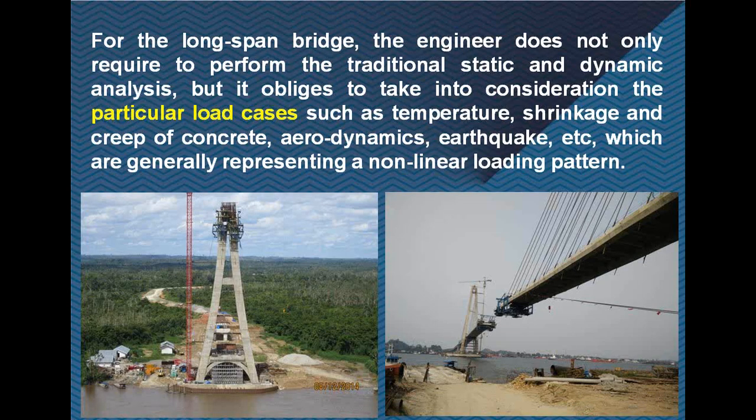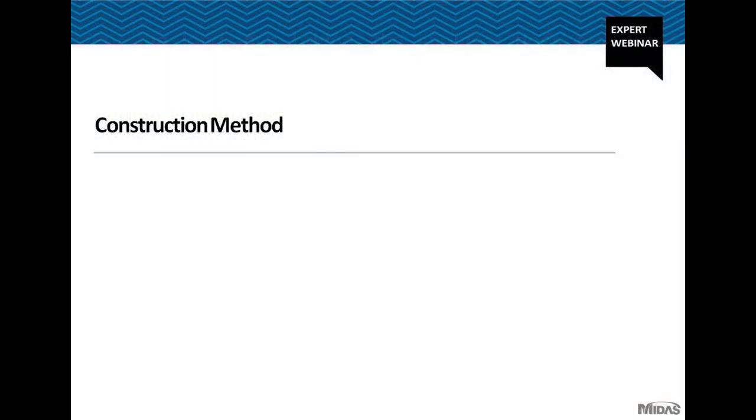For the long span bridge, the engineer doesn't only require to perform the transitional static and dynamic analysis, but is obliged to take into consideration the particular load cases such as temperature, shrinkage, and creep of concrete, aerodynamics, earthquake, etc., which generally represent a non-linear loading pattern. How is the construction method?